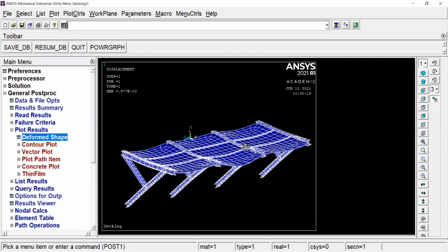Is the offset command hard? It's a bit confusing because you have to know what face is positive, what face is negative for these shell elements. In this case, the offset won't change anything. It won't change any of the forces that are being experienced by this model, because we're working with very simple elements, just beams.